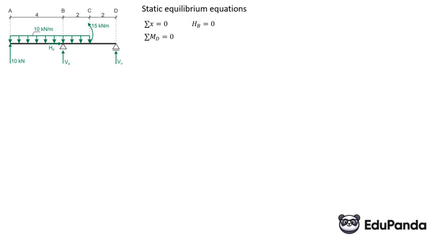So we have a rectangular load. There can also be triangular loads, sometimes trapezoids as well. But most often it is a rectangular load, that is, a continuous load with a constant value. So we can imagine that this 10 kilonewtons per meter is the height of this rectangle, and 6 is the length, 6 meters. So we can find such a resultant. If we multiply the 10 kilonewtons by 6 meters, we are actually calculating the area of this rectangle. And from the units, we also see that the unit is kilonewtons. Because kilonewton per meter times 6 meters gives us 60 kilonewtons.